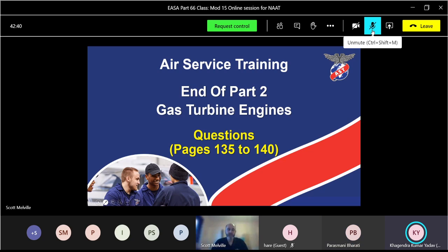For aircraft discrete, that is WOW. Yeah, weight on wheels switch. So one is in the cockpit, where the person is actually moving the switch yourself. The aircraft itself, it's a micro switch. It's mechanically moved. Physically, we can't lean out of the cockpit and switch it off. It's all done by the aircraft. Good. How many power supplies are there to the FADEC? Two. Yeah, your standard DC supply, and then when the PMA kicks in, at 50%, we'll get the alternate on there.